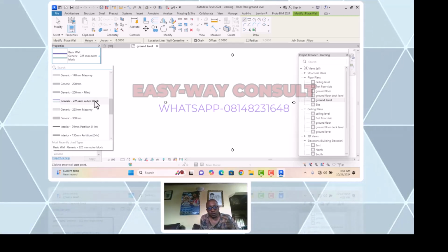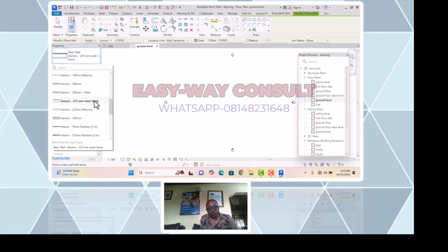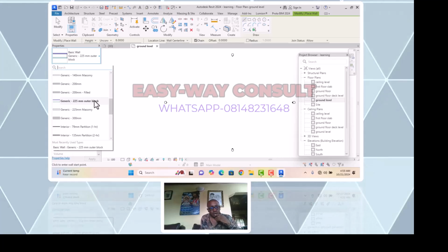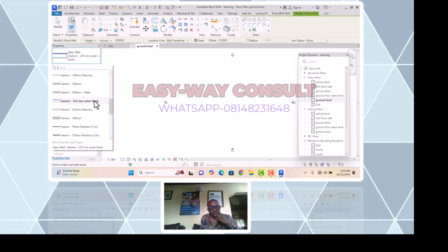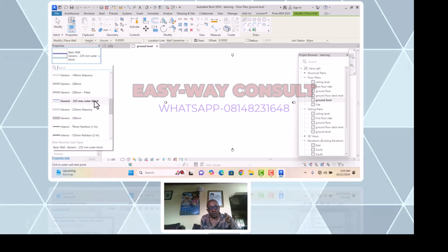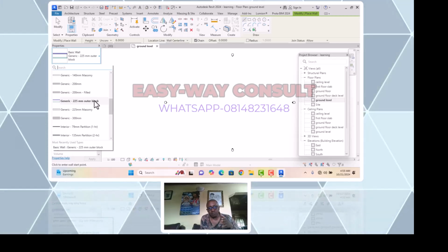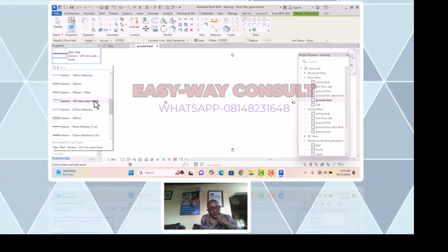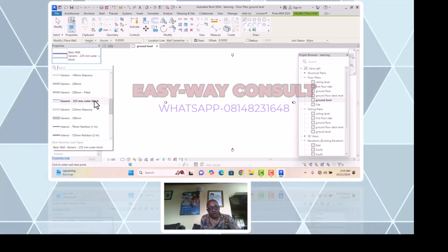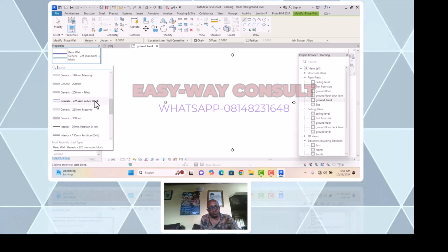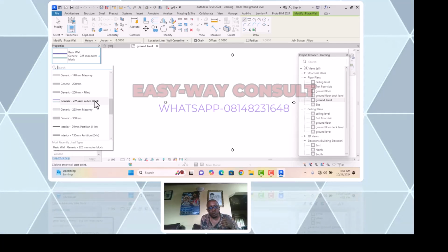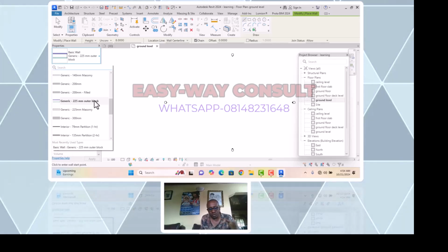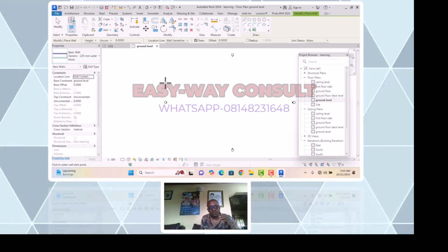We are going to create another wall that we will use for the partitions of the building, and that will be 150 mm. That's 5 inches block. Then when we design that, we also have to put the colors. We have to select the materials of it, just the same way we did this one. We are going to do it in this lesson too.